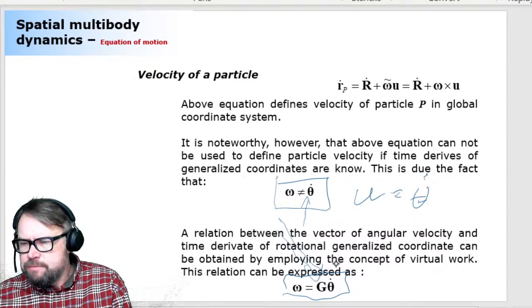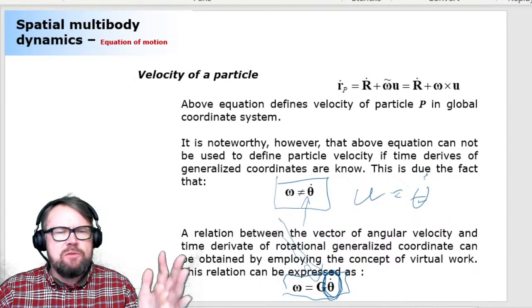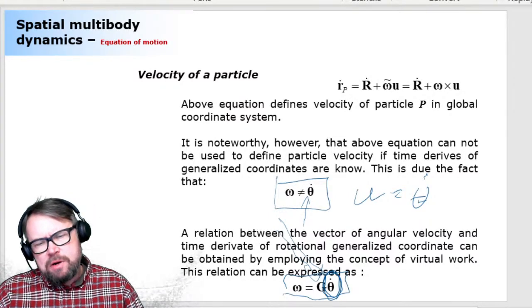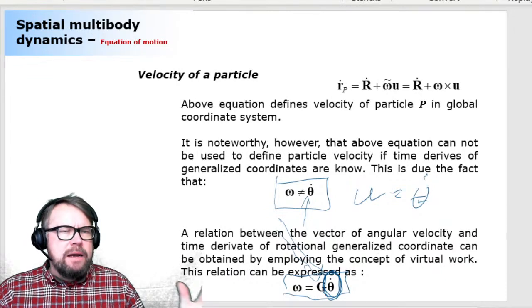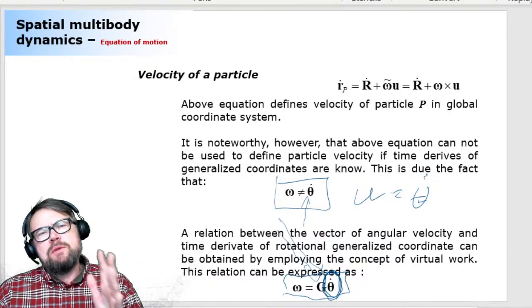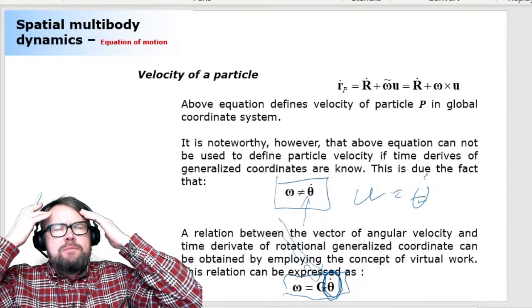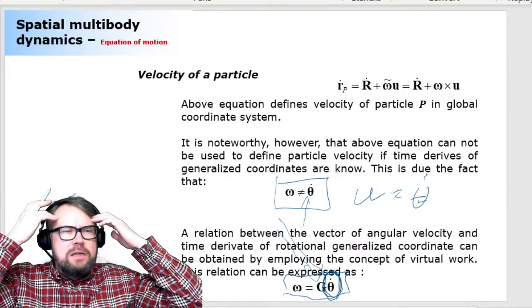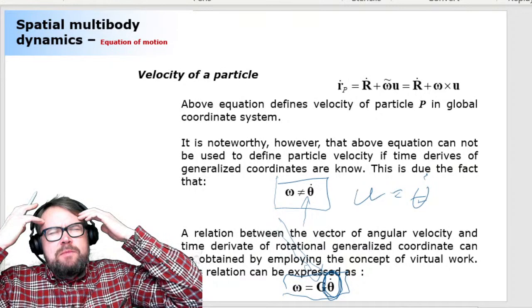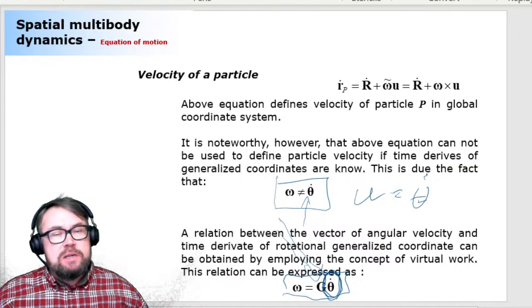Because this guy here, what we are using in a computation, there are several different choices for how this could be expressed. It could be Euler angles, it can be Euler parameters, and many other ways. Now, expressing inertia properties in terms of Euler parameters, which are 4 parameters, will be a great challenge because, first of all, we lack knowledge of how they behave, so human brains are not trained to deal with that. So how can you express mass moment of inertia and mass product of inertia with respect to something that you don't even understand? That's going to be very difficult.